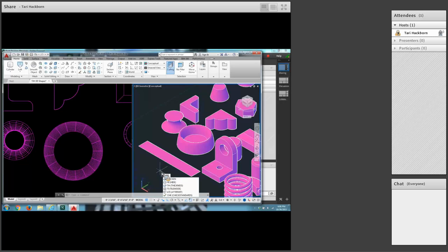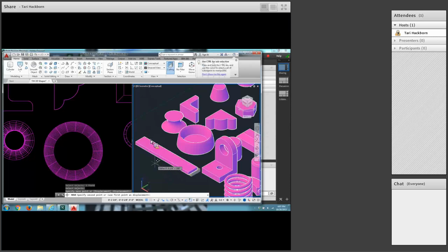THICKEN, and enter. Then click the surface and enter. And type 1/8. That's your planar surface. I would much rather use extrude or presspull. I might have to move mine back a little ways here. Okay, that's the planar surface. I'm not impressed. Okay, the polysolid.